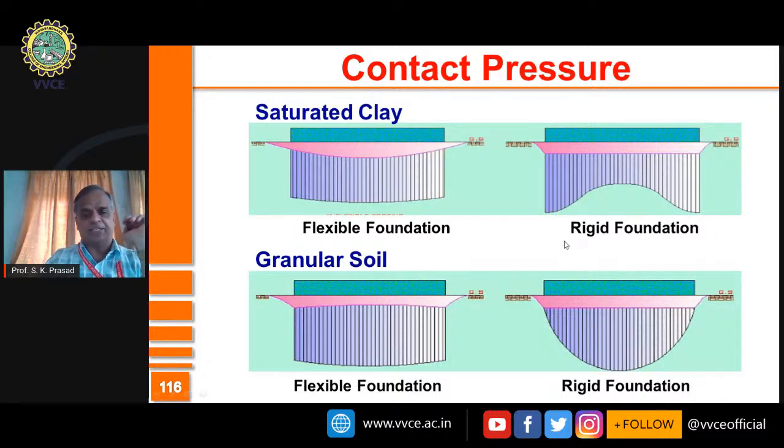And if you see the other extreme, that is when you consider the footing to be rigid, you will see that the footing is rigid, it doesn't bend. The contact pressure is not going to be uniform. Contact pressure is more at the edges because of the edge stresses in clays. On the other hand, the contact pressure will be more at the center in sandy soil or granular soil because of the confining pressure effect. Therefore, the two types of soils, clay and sand, show different behaviors.